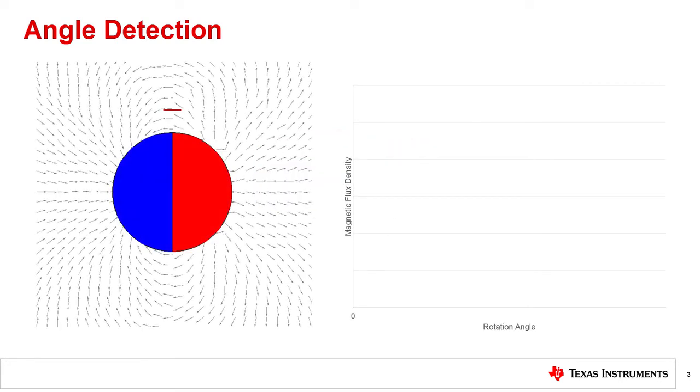If we consider a top-down view of the field vectors produced by this type of magnet, we can observe curvature of the field around the magnet. With any Hall element, only the component of the vector which is orthogonal to the sensing element will be sensed.